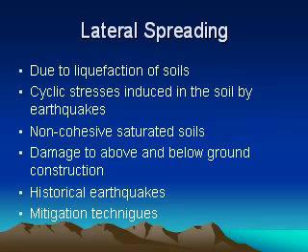We learned that damage in liquefied soils can occur above ground, such as to buildings and bridges, but it can affect the below-ground aspects of those as well, such as the footings. And with roadways above ground and below ground, we have lifelines that can be affected as well. Historical earthquakes, like we said, any significant earthquake that you've heard about in the past has probably experienced a lot of lateral spreading. And can we totally eliminate lateral spreading? No, but we have techniques that can help mitigate lateral spreading.